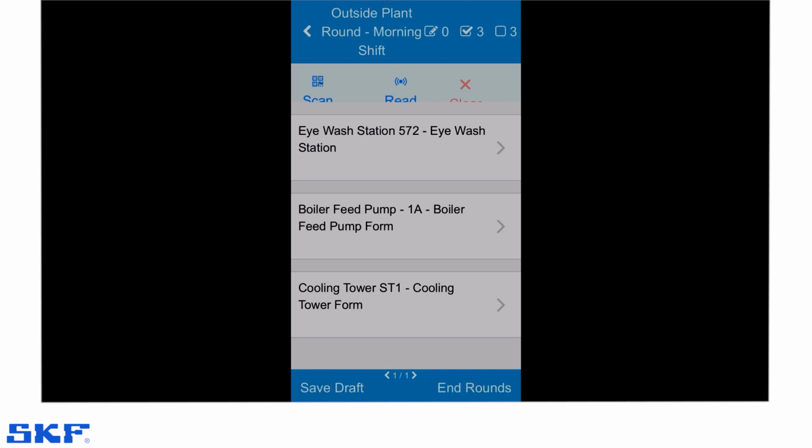So I will make a note that with that acceleration enveloping and the velocity being out, I automatically receive an email when something is wrong. I'm going to show you that example when we get out of this. But just let you know that is another thing that could trigger if you want that email sent about this asset and it's starting to vibrate way too high, temperatures way too high, whatever it is, those alarms can be set and make sure you have eyes on it right away.